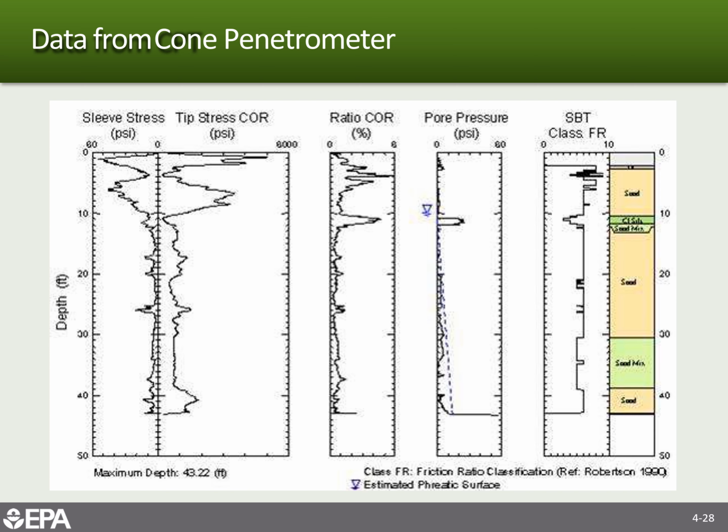So this readout here can then give you the lithologies in the subsurface from pushing this tool through those zones. And the pore pressure pops up when you're in this clay zone here, and you can get that reading as well.